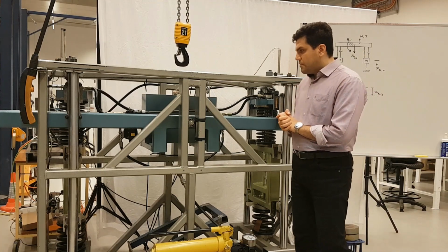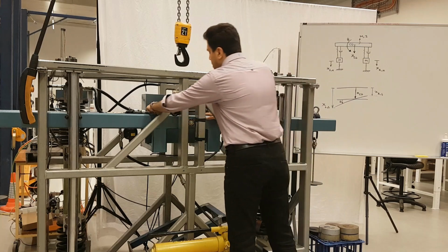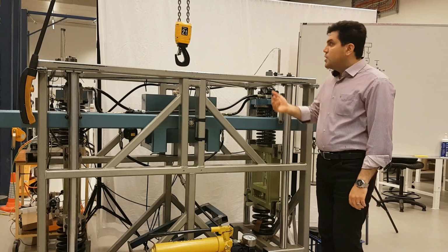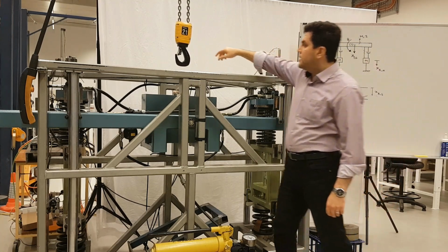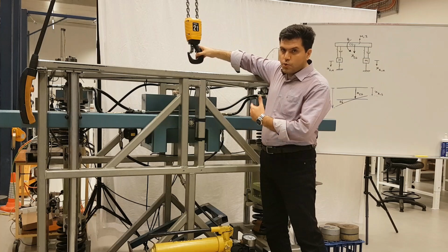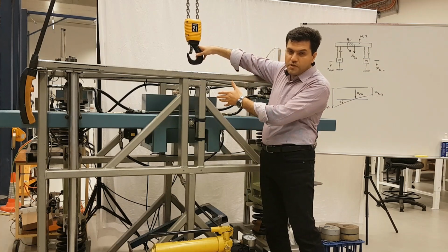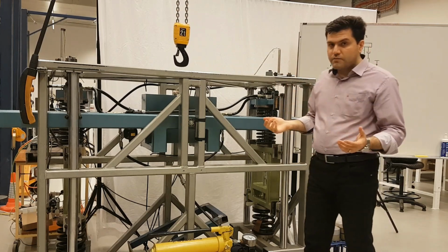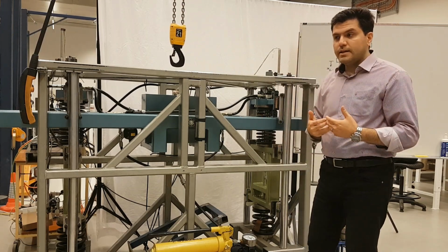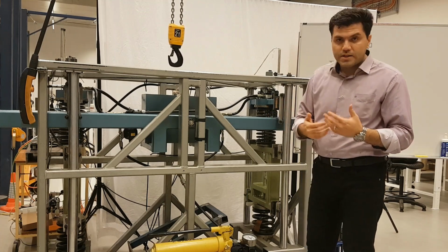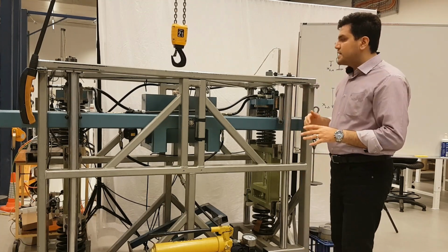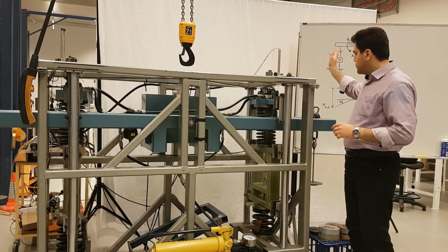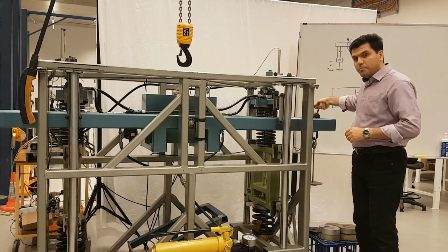The first mode of vibration here is the bounce mode. How do we excite the bounce mode? We use a crane. This is the crane, and this is the hook of the crane. We move it down, and then we lift the spring mass up and release it from the center of gravity. In this case, we are able to excite the bounce mode only. For exciting the roll mode, we move the crane to, for example, this side, and then we lift it up from this side.